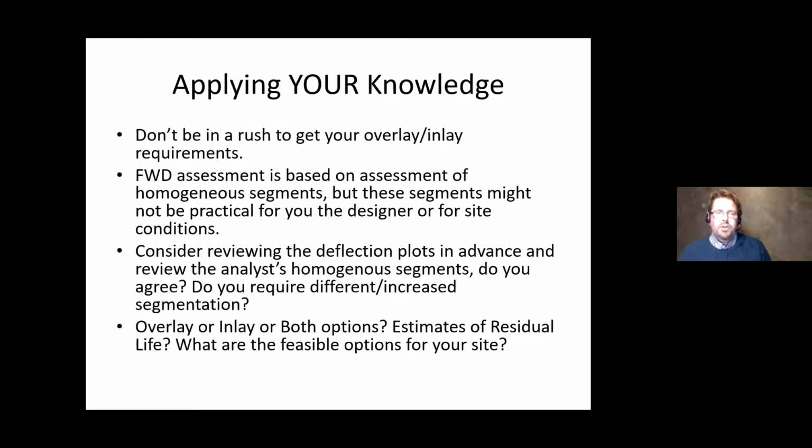So I'm saying, don't be in a rush to get your overall FWD overlay and inlay requirements. It's based on homogeneous sections, but be conscious that the sections the FWD analyst is giving you mightn't be practical for you, the designer, or for the site conditions. You mightn't be able to overlay here. You might be curtailed by curb heights, by approaches into town. Likewise, you mightn't be able to do full depth inlays. You could be crossing a bridge.